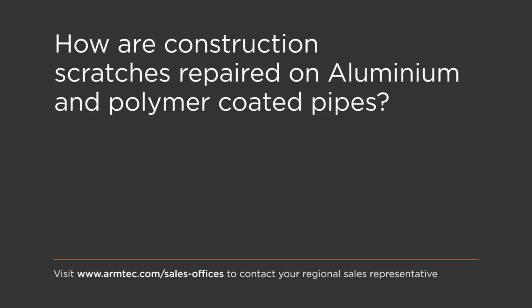Well, for aluminum and galvanized coated pipes, you would use a zinc-rich paint or primer. There isn't an aluminum type paint out there, so we use that paint even in our shop to touch up aluminized steel culverts. And for polymer laminated culverts, the best solution is to use a butyl tape.